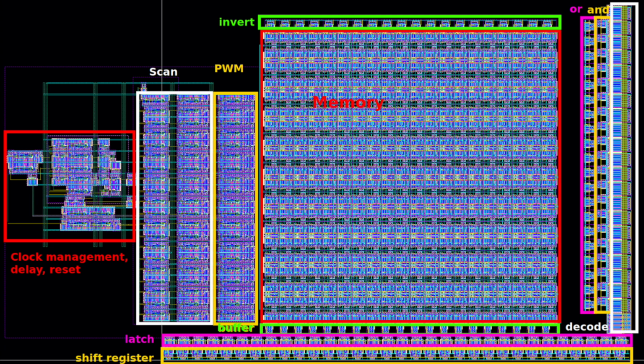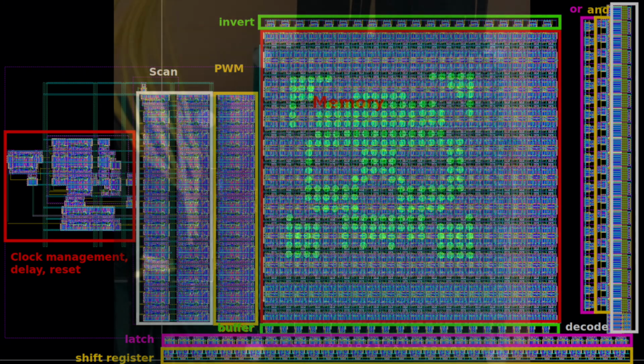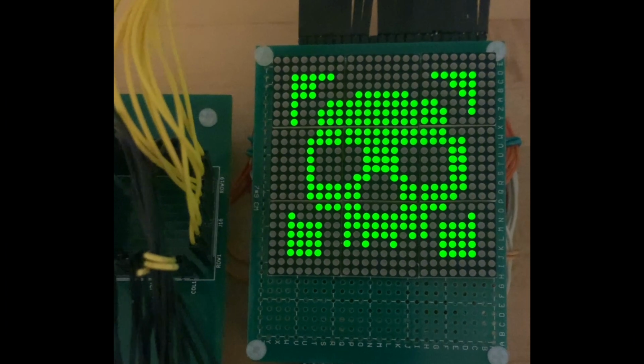In the remaining part of the video, we will show some testing to further demonstrate what the chip is capable of and how it works. The first clip shows the row scanning behavior of the chip. As explained previously, the passive matrix design allows for one row of the display to be illuminated at a time in order to reduce the number of I/O pins required.